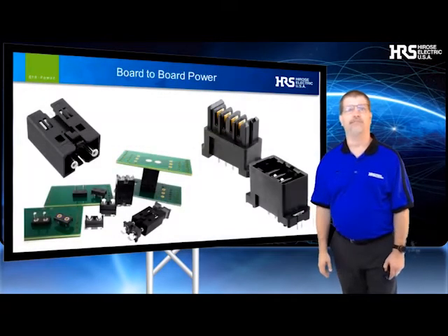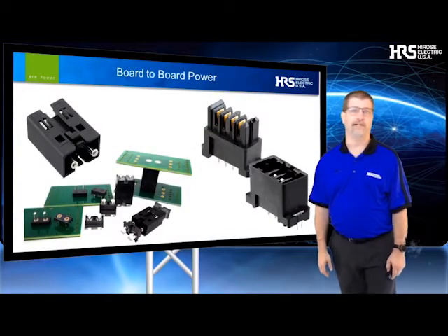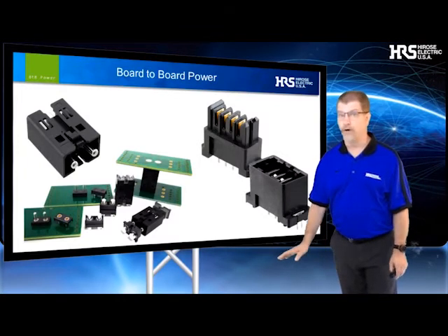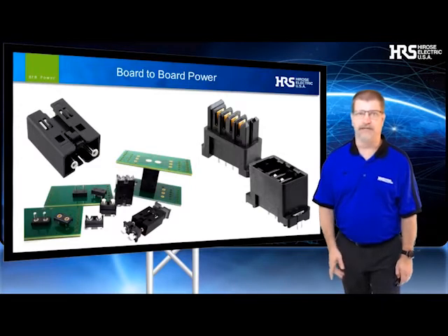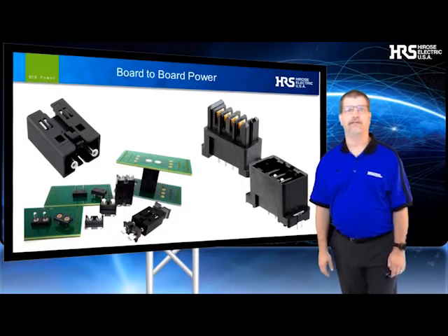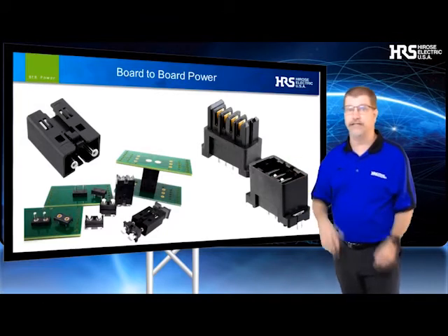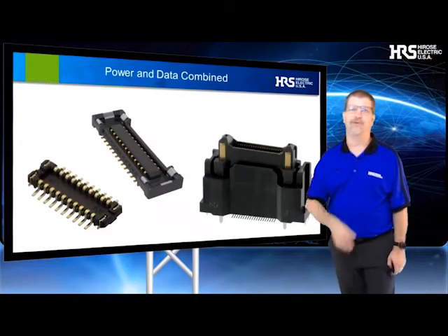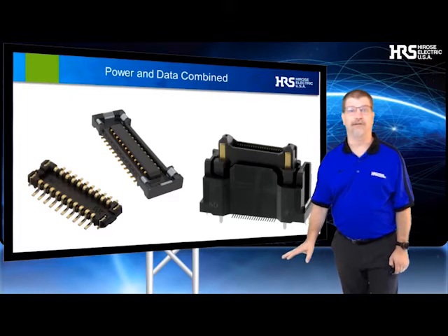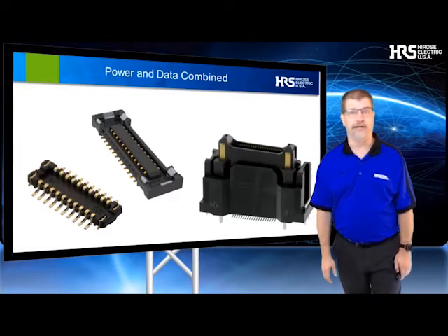Finally, I want to mention board-to-board connectivity as it relates to power connections. Traditionally, these connections were either data or power, but not both. Designers would combine contacts together when they needed to deliver more current than just what a single contact could handle. Today's board-to-board connectors offer many choices for combining power and data into a single connection.